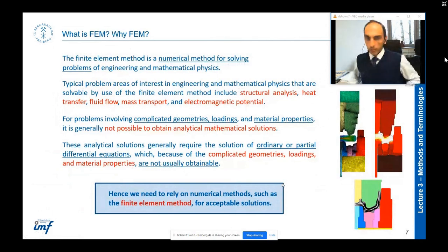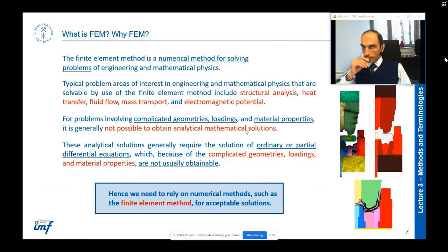We talked about the simulation. Now, what is FEM, or finite element method, and why do we use FEM? For simulation, we can use different methods. We have the finite difference method and finite volume methods, which are usually used for flow simulation, for CFD simulations, and we have the finite element method, which is used in our case because our concept is metal forming. We use, not usually, but all the time, the finite element method.